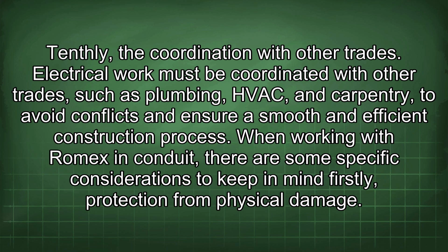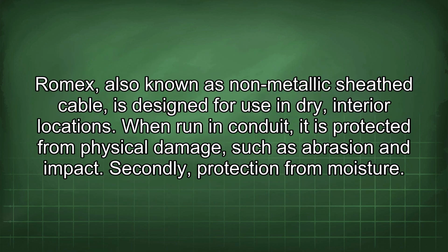When working with Romex in conduit, there are some specific considerations to keep in mind. Firstly, protection from physical damage. Romex, also known as non-metallic sheath cable, is designed for use in dry, interior locations. When run in conduit, it is protected from physical damage, such as abrasion and impact.